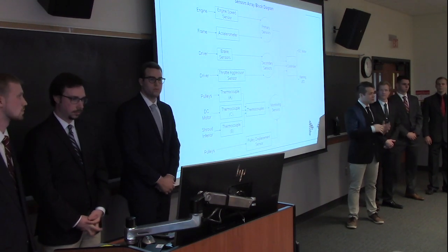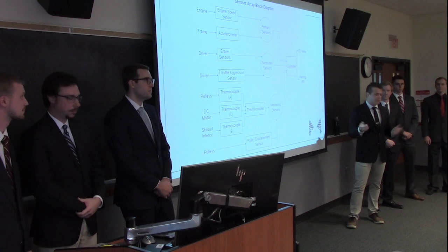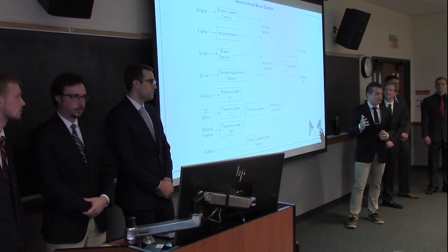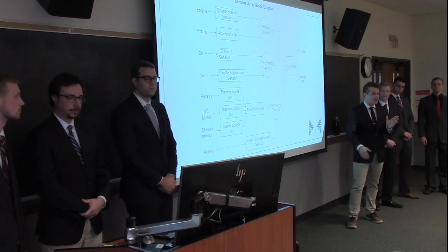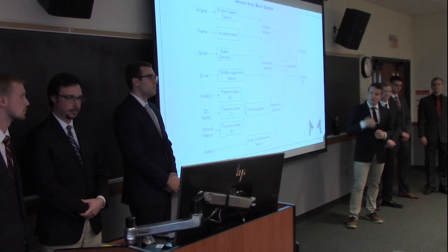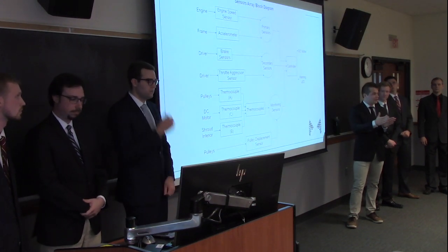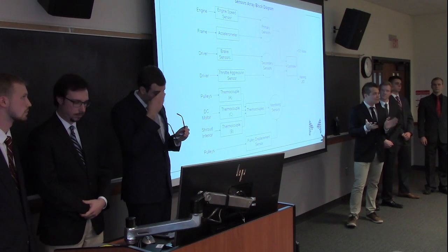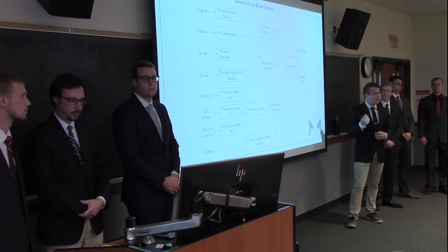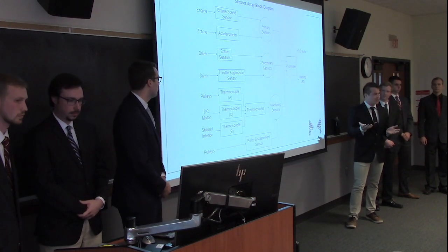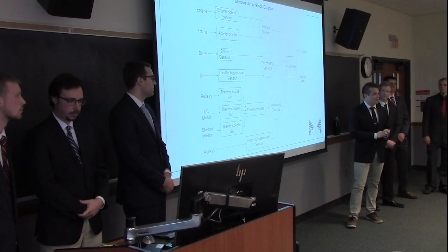The next sensor is the accelerometer. The accelerometer measures G-forces on the vehicle, and what it basically is, is a really small PCB, standing for printed circuit board, and it has 3 capacitors on it, one in the X direction, one in the Y direction, one in the Z direction. Those capacitors have a fixed side to them and a side that can flex ever so slightly. So as an acceleration force is applied to the PCB, the side that can flex moves ever so slightly. As it moves, that changes the capacitance because the distance between the plates is changing. That change in capacitance can then be converted through an algorithm to force being applied to the vehicle. The accelerometer is then mounted to the car frame closest to the center of gravity to give us the best readings.